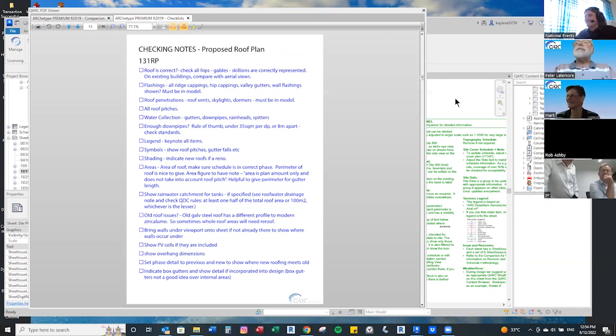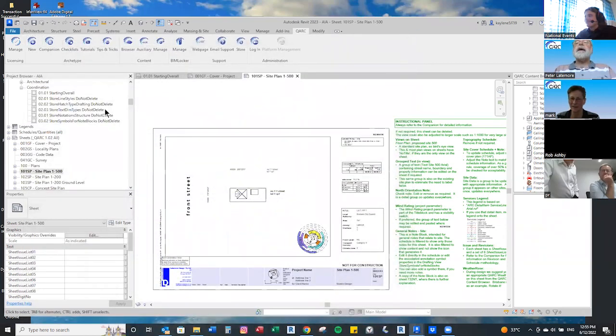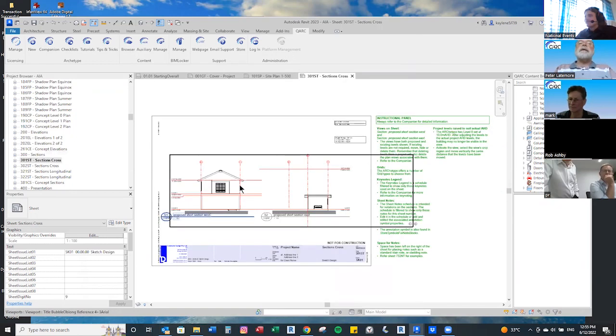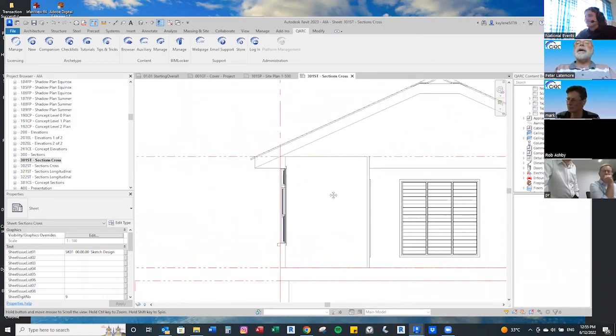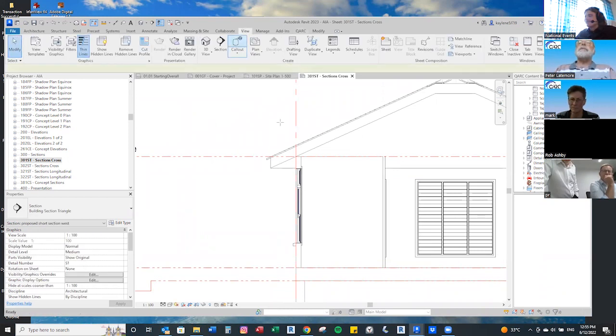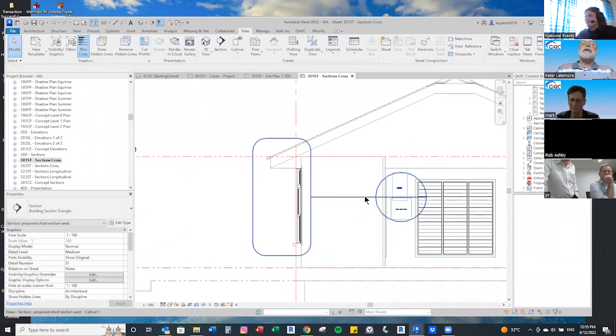And we would strongly suggest you get used to detailing in Revit itself. If you have standard legacy details, that's okay. Get used to bringing them in from AutoCAD, adjusting them to suit, and then away you go. By the way, in the Archetype, we have included some details that we've obtained from third parties, and you can use them and begin to understand how to do it.